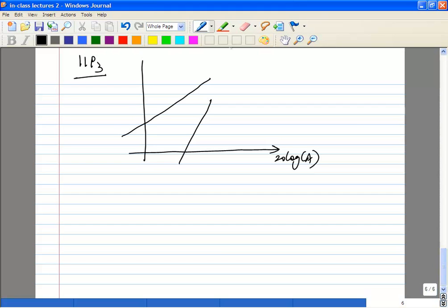Now in reality this will compress, and similarly, because of higher order nonlinearities, you will actually see compression even in the third order, because you will have even higher order odd terms coming down on top of your third order. So if you extrapolate these as a straight line, you get a point which is called the IIP3, and this is called the output referred intermodulation product.